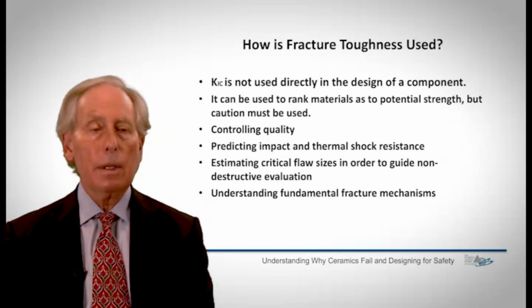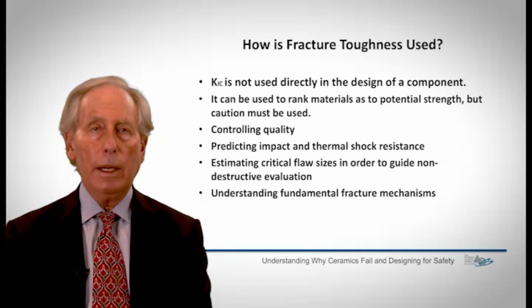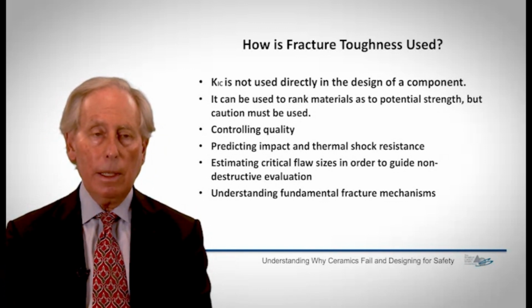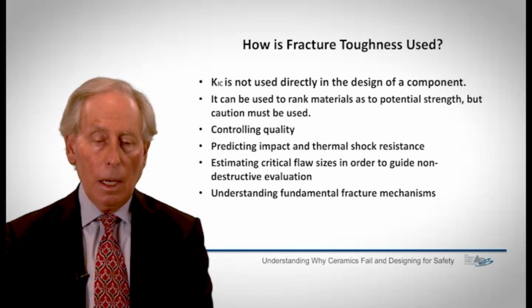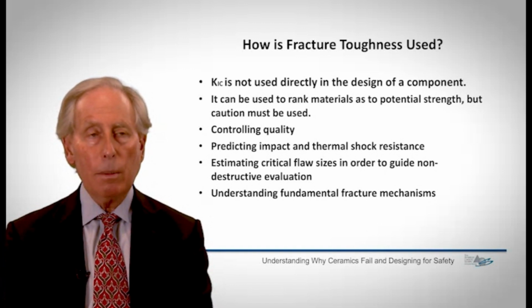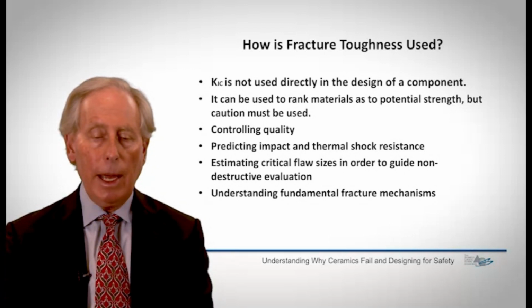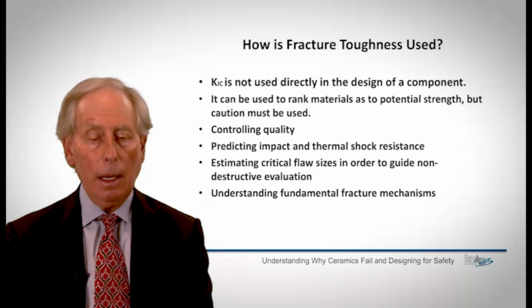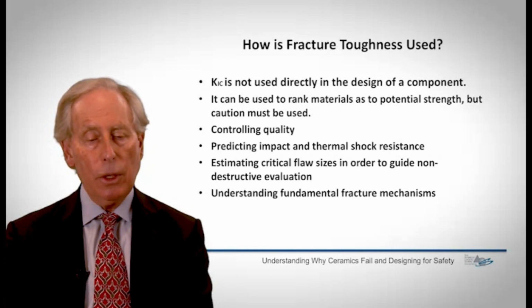How do we use, now that we know what fracture toughness is, and I will show you later how we measure it, how do we use it in our engineering profession? Well, it's interesting. Critical fracture toughness isn't really used directly in the design of most components. There are better ways to do it, namely strength, but there are conditions and cases where the application demands that I find what the critical fracture toughness is. I'll show those. But it can be used to rank materials.